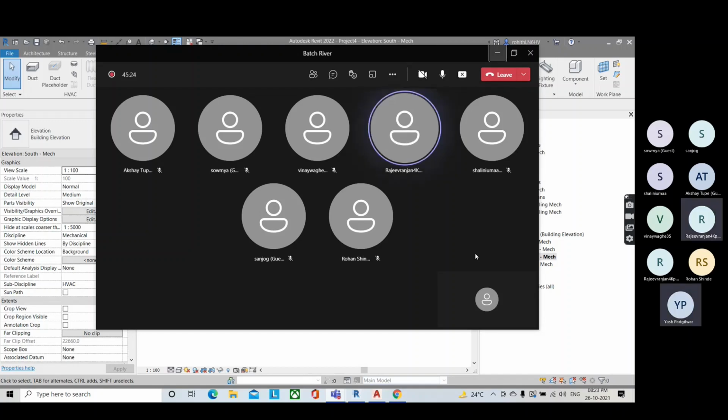In T shape, the connection is meeting both pipes, but in beveled shoe shape... No, what I'm asking is, under what category does this beveled and shoe type come? Tap fitting, right? That's a tap type fitting. Okay. And after that, we saw the transition type. And what is transition? If two pipes have different dimensions, there we will provide a transition connection. Okay.